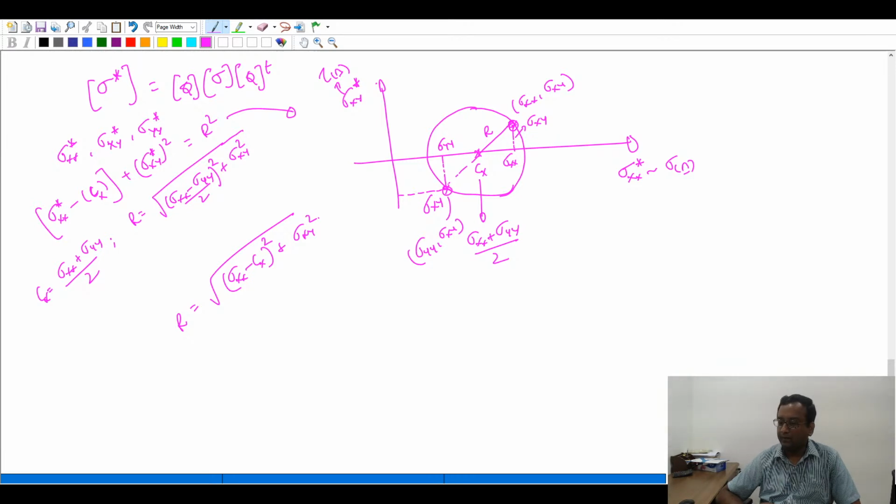See, when something punctures the other, one thing is supposed to be rigid compared to the other. The one which is rigid is the column here. So that's why the column punctures the slab and not the other way around. And you don't draw horizontal force diagrams, you draw axial force diagrams. It's not only for bars, even if you have a frame structure, you draw the axial force diagrams.